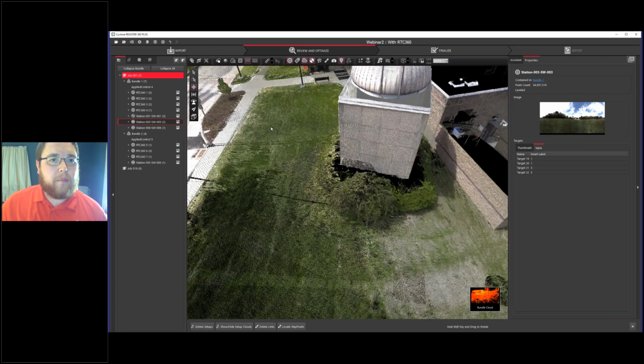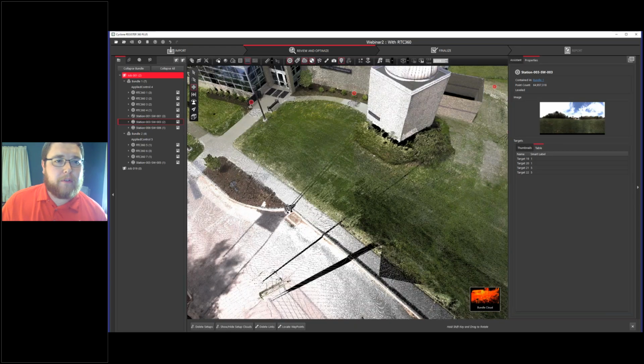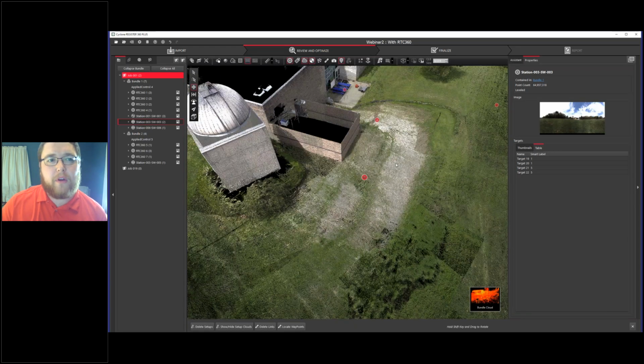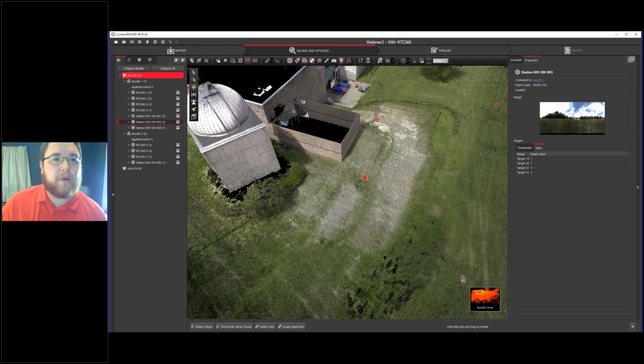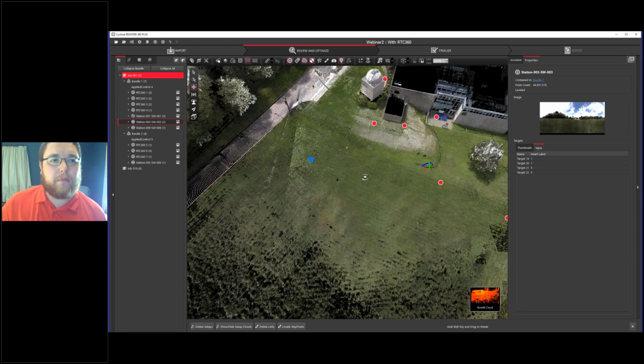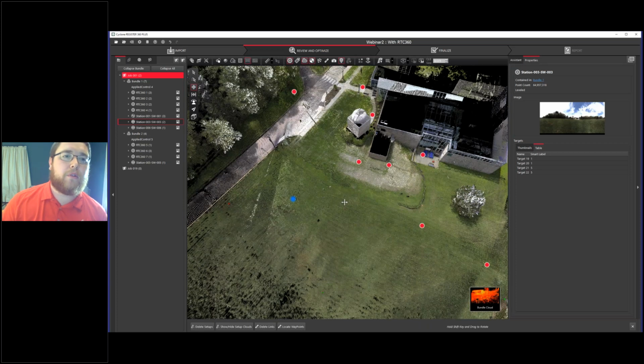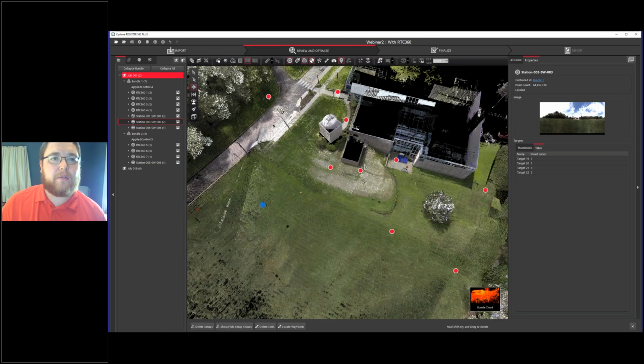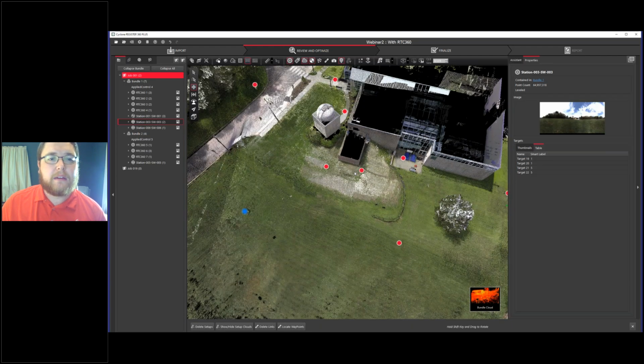So I used RTC for those extra scans. There's no reason you can't do this all with a P-Series scanner, and do those couple scans where you tie into 3 or more control points, and then your other scans go, okay, now as I'm filling in, I'm going to rely on the cloud to cloud and work with that here in Register 360.